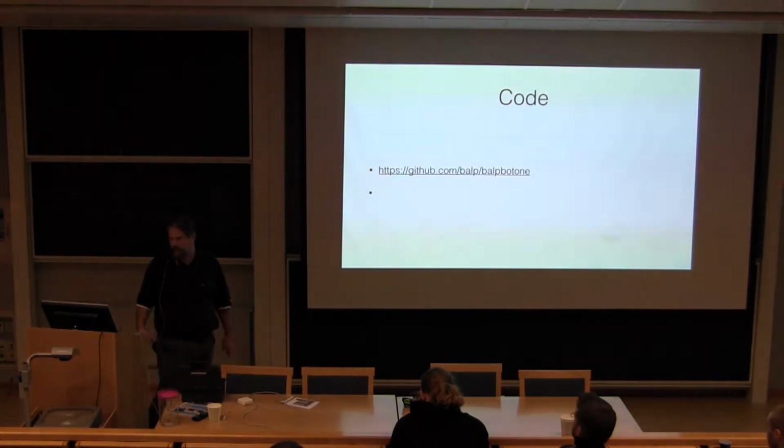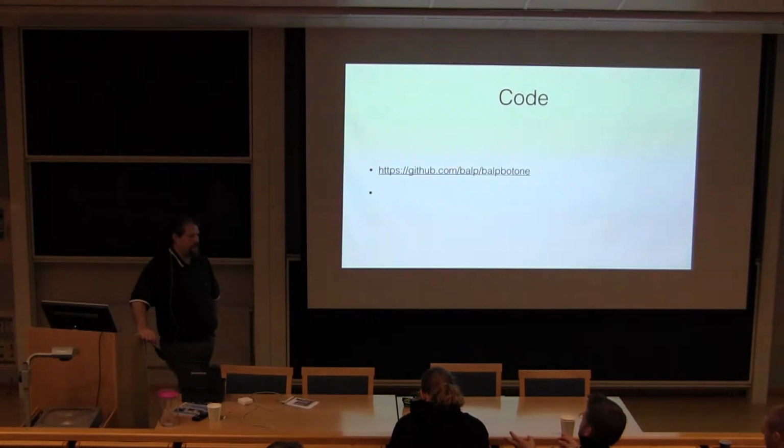So that's another library I have put in. It's basically a command line thingy to upload. And most of the time I'm using GNU make for actually building. So it's the GNU make command, make upload, and it uploads to the connected Arduino.